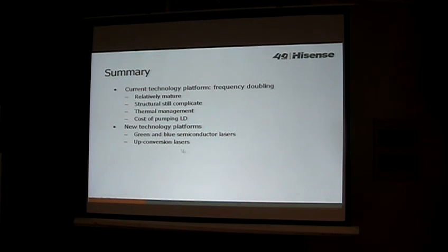Like we said, this is the simplest, most straightforward one. Unfortunately, we have explained we cannot get efficient light emission from semiconductor material for green and blue, especially for green. Either because the material system becomes an indirect bandgap material at green wavelengths, or because the mismatch between the substrate and the epi layer becomes too huge, introducing a lot of defects, so the efficiency is reduced.